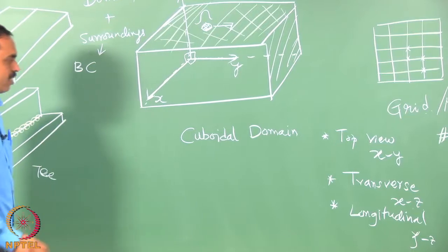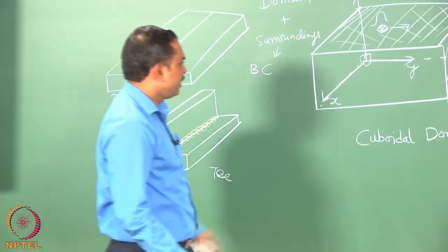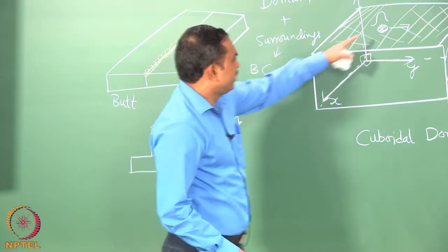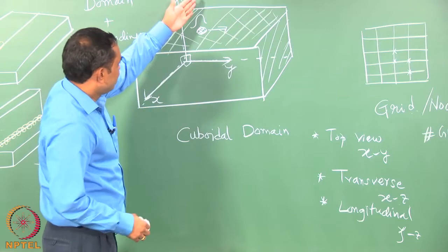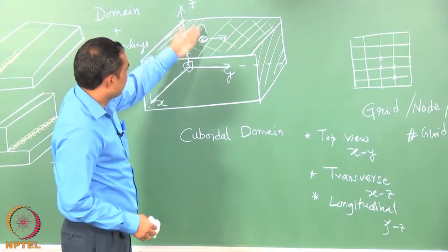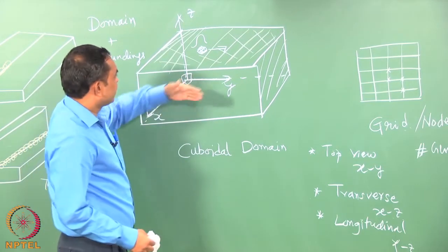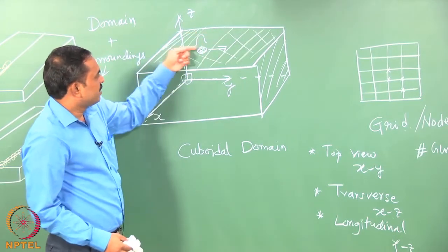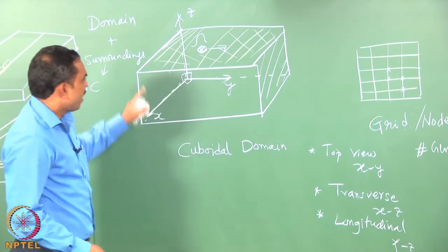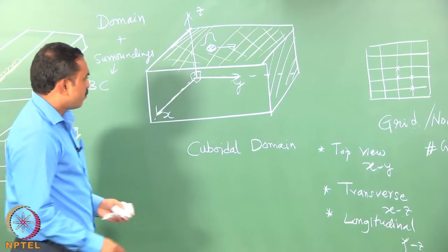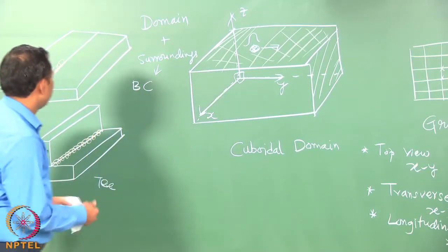Okay. So, the information that is contained in each of these sections is as follows. In the top view, you have basically the heat source, and in the transverse view, you have basically the section of the weld pool at any given instant of time, and in the longitudinal section, you have basically the vector that is containing the transverse motion of the heat source along with the region that is molten and solidified. Okay. So, a quick schematic would show you how they would look like.